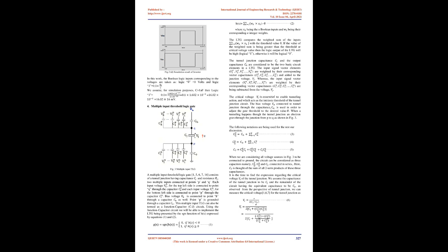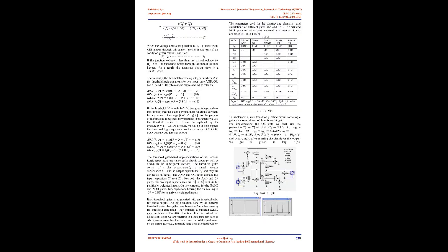How does it happen? We set the voltages V1 equals 0, V2 equals 16 mV, along with the tuning gate voltages, at present, both for SET1 and SET2. Now if the input is logical 0, SET1 is in conduction mode and SET2 is in Coulomb blockade. This results in the output being connected to the bias voltage and causes the output voltage to be high.